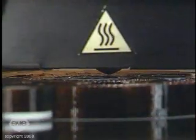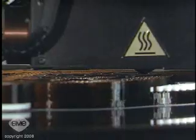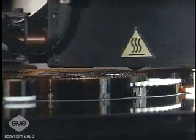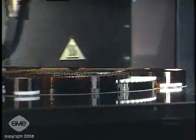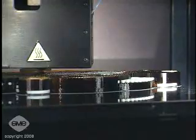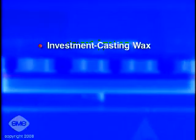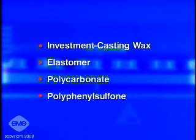The most common material used for fused deposition modeling is acrylonitrile butadiene styrene, or ABS thermoplastic, in various colors. ABS provides tensile strengths of up to 5,400 pounds per square inch. Other materials used include investment casting wax, elastomer, polycarbonate, and polyphenylsulfone.